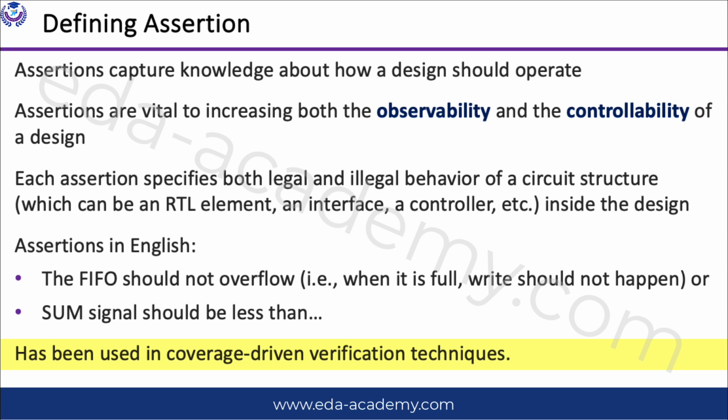Assertions have been introduced into coverage-driven verification technology as part of checking verification completeness. By adding assertions to the verification environment, we can check whether the design functionalities to be verified have been toggled by the stimuli in the test cases and analyze whether there are any coverage holes in the verification environment.